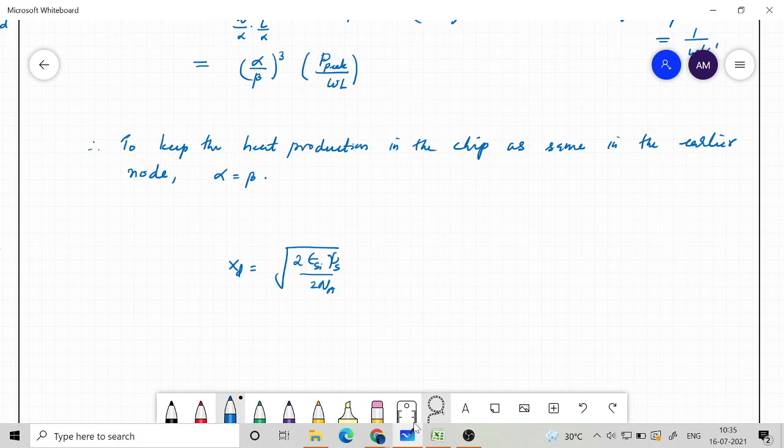So in other words, the depletion region width depends on the potential that is dropped across. Depending upon the potential that is applied, the depletion region width changes. It could be a built-in potential of a PN junction, or this formula is general, where psi s is basically the potential across the junction.